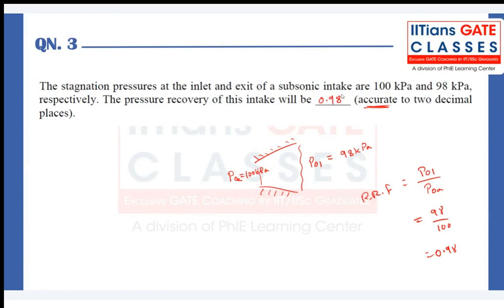Because we assume these ducts to behave as isentropic in an ideal condition, or at least we model it as an adiabatic process. So we know for an adiabatic process, the total temperature is going to be constant. Again, this is a very, very important definition, the total property, the total temperature. The moment I say this, the inherent assumption which comes along with it is the flow is steady,